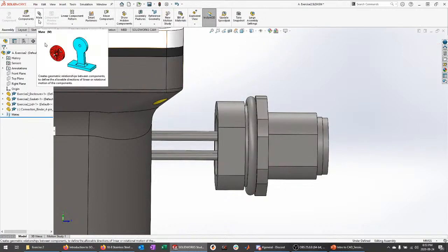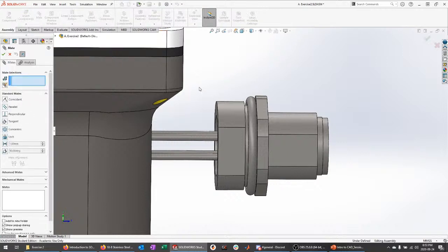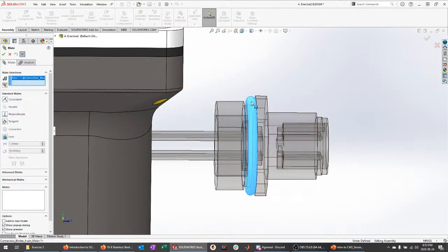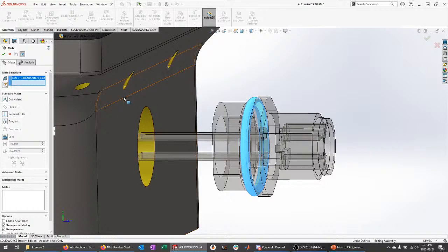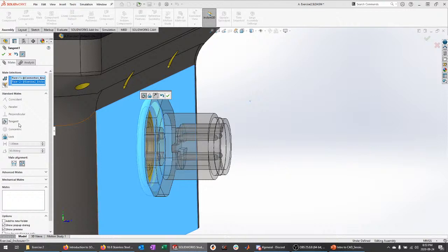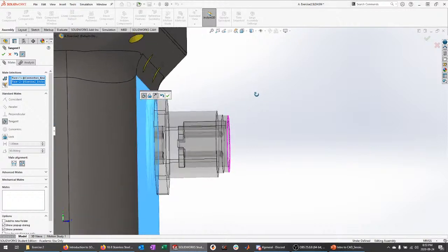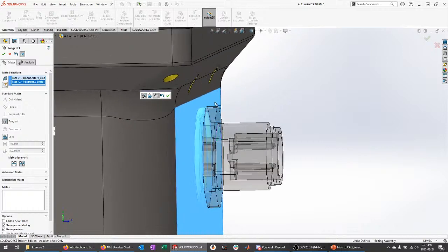So in actuality, in CAD, all of the solids that we model are rigid. That means you have some choices when it comes to modeling deformable bodies. In this case, we're just going to select deformable bodies like O-rings or gaskets, to clarify. We're going to select that face, and the mate tool will actually assume what we want. I'm going to select this face here, and it will assume correctly that we mean that toroidal surface and that flat plane to be tangent to one another.